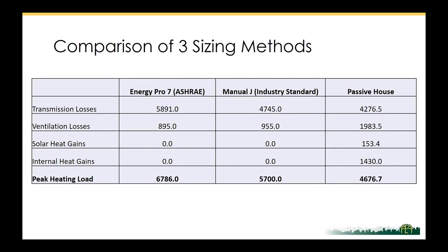The existing wall furnace is 20,000 BTUs per hour. These are significantly less, so not only can we install an electric clean heating device that's higher efficiency, we can also install it at a much smaller capacity, which would be significant on the energy efficiency side.